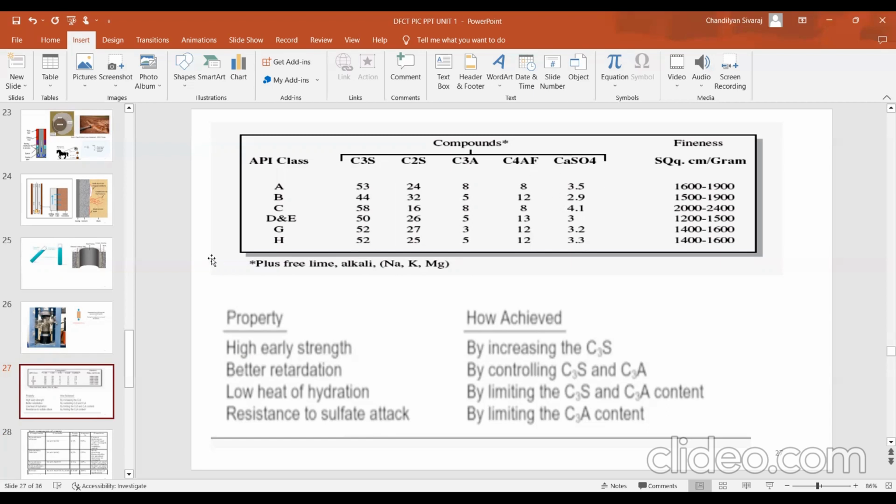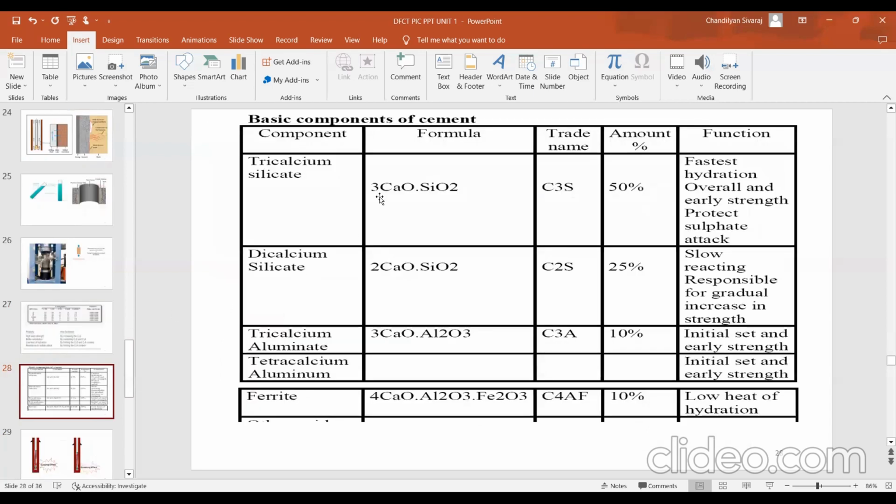and CaSO4 is easy for you, calcium sulfate. For that, I put this slide here. What is C3S? Let's go from right to left. C3 means 3 of calcium oxide and 1 of silicon dioxide. 1 is missing here. We can miss it out. It's not necessary to write 1 here. So how much is the calcium part? 3 times calcium oxide and 1 time silicon dioxide.